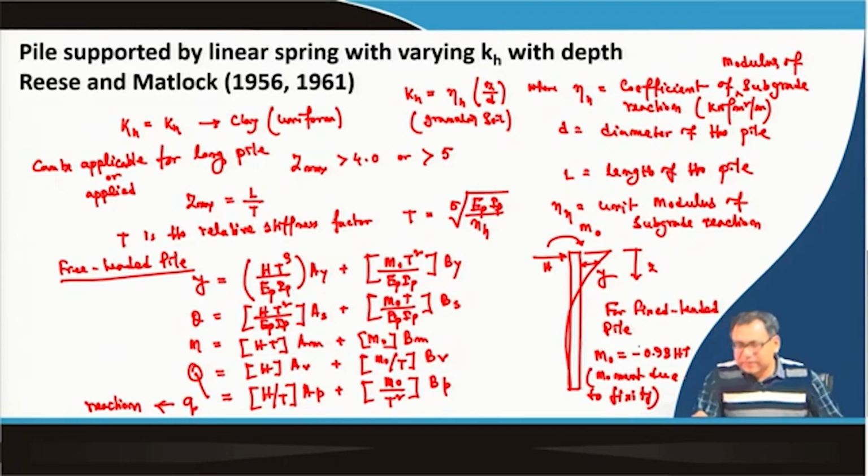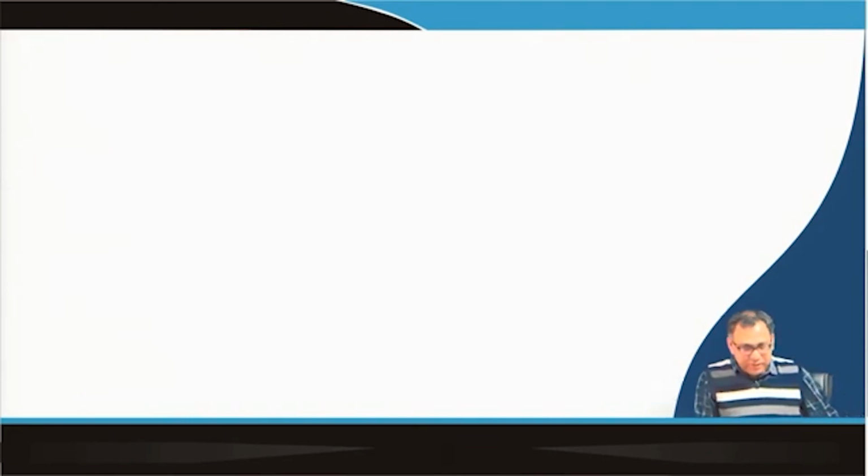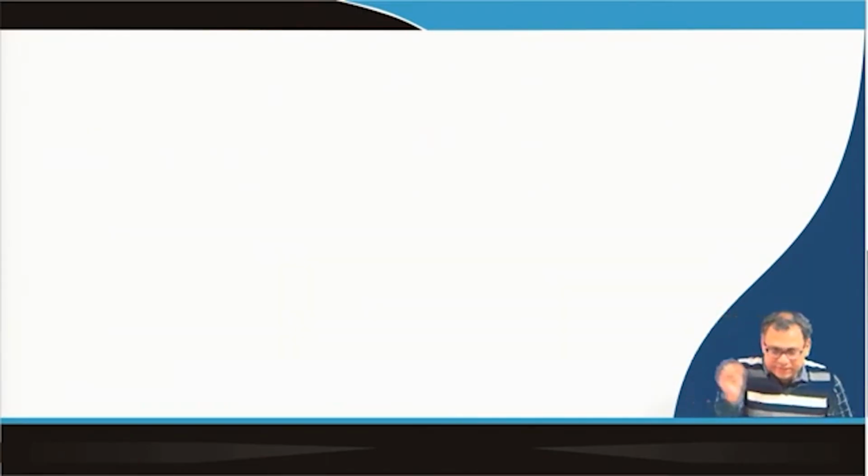So, that means for a fixed headed pile, a moment will be generated due to the fixity, which is minus 0.93 h t, where h is the horizontal load which is acting. So, now let us solve one problem, and we will see how we can determine the deformation for a pile where k h is varying with depth.